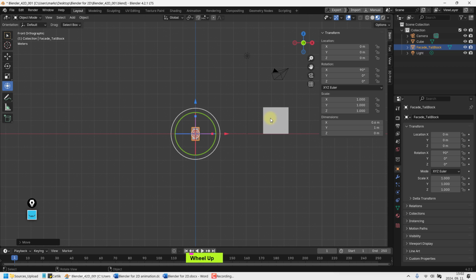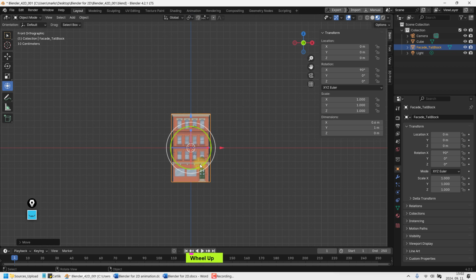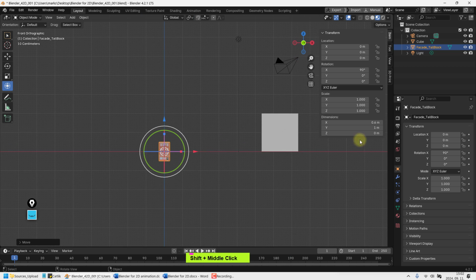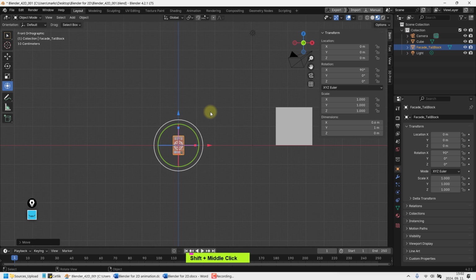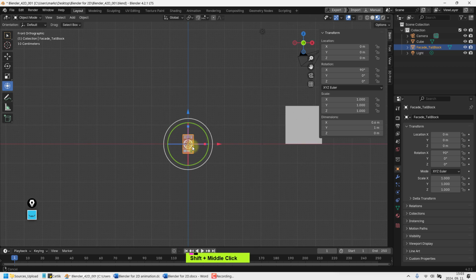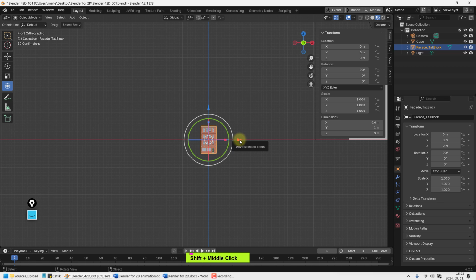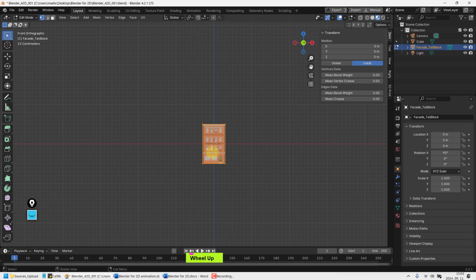So what else can we observe? If the cube is 2 meters, that means this door is about 2 centimeters. So we definitely have to scale it up, and this is 1 meter, so it's a 1 by 10 at the moment. Now before we do the scale, if you just start scaling, it will scale at the center point. There's a better solution if you right away change the pivot point, and in this case you don't really want to move it because it's already on the ground, but you want to select the model.